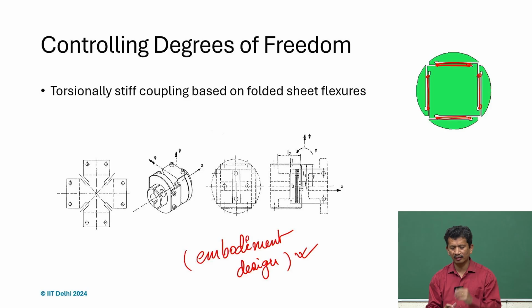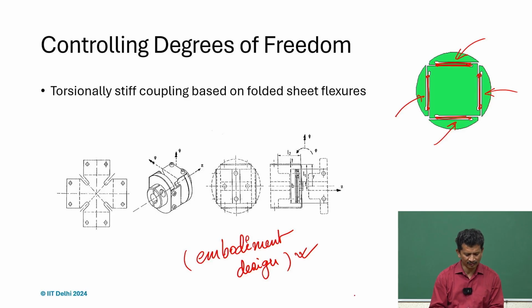Out of this big thing, that tiny part is the functional element, which provides the required constraints but at the same time also provides flexibility, and that is how you release the 5 DOF, which if constrained would be over constrained, and then we may have to give some tight tolerances. So, be aware of that.